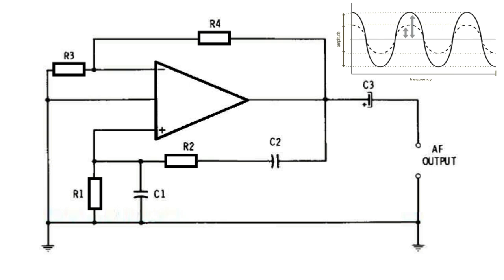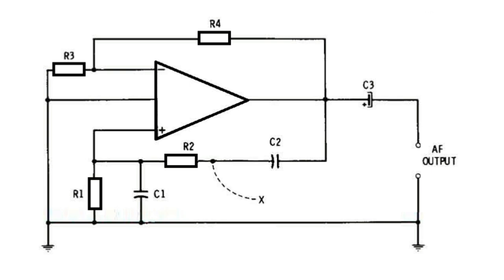Nevertheless, this varying tendency of the amplitude could be decreased using an appropriately dimensioned non-linear resistor, for instance a thermistor, varistor, or double-ended Zener diode, hooked up between point X and ground. Controlling the output of the oscillator can be executed through a potentiometer, which may be either incorporated into the output or placed between the stages of the IC.